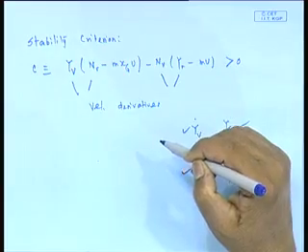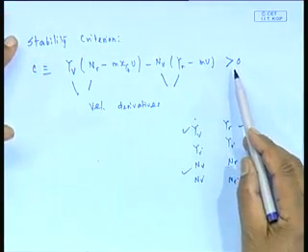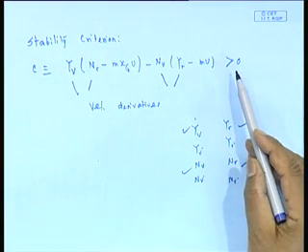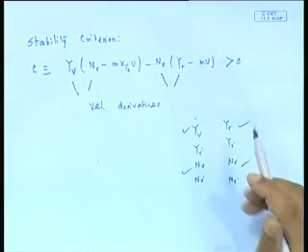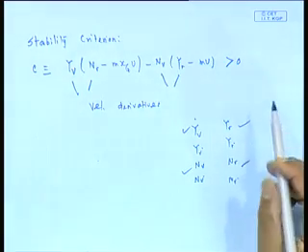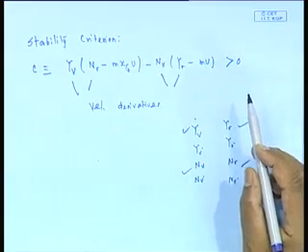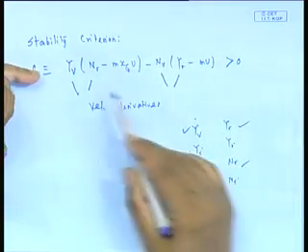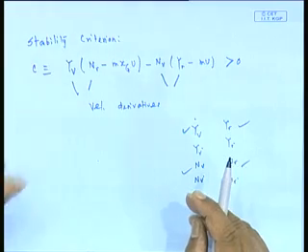Then I have to ensure that this value is positive. Again design conditions come in. If I make it very positive, then it becomes so stable, like a very stiff cycle, that turning will require more effort. On the other hand, I also want to turn, so I want to make it positive but not much positive. In other words, how much this value is more than zero, which I will come to later on,